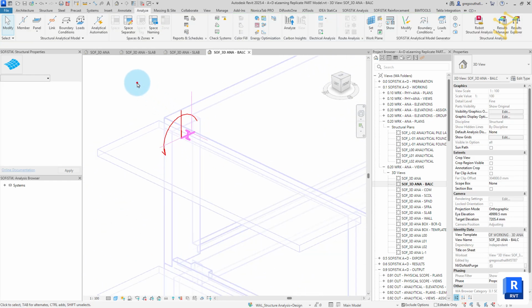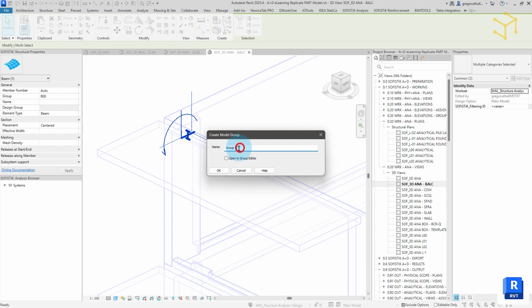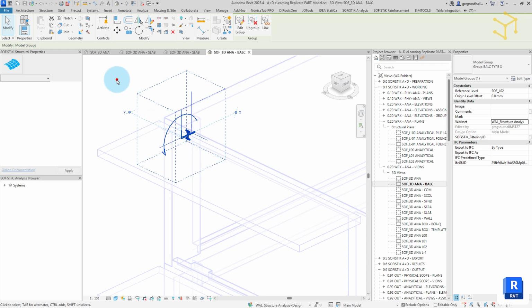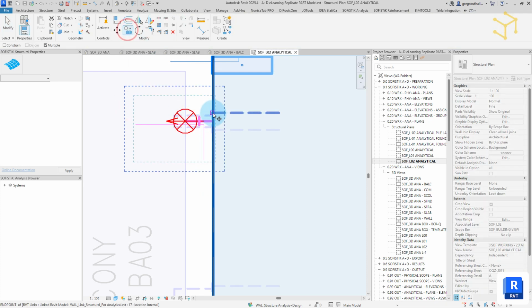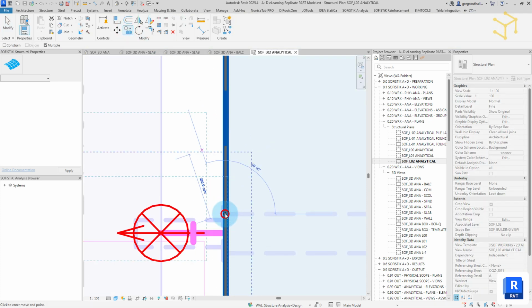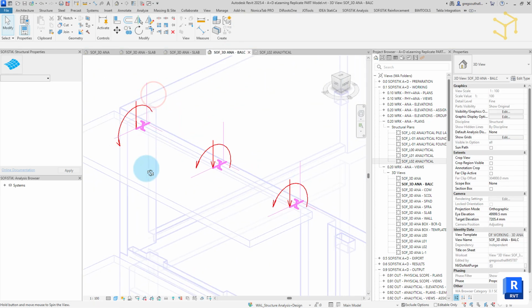Optionally, we can create a group for subsequent copy and pasting as shown here. Copying and pasting is better carried out in a 2D view. For balconies, a local coordinate approach is preferred, especially when copying a group and reorienting the element to different elevations. You can now continue your learning by carrying out the gravity load application exercise on your part model in accordance with the load values contained in the documented load plans.